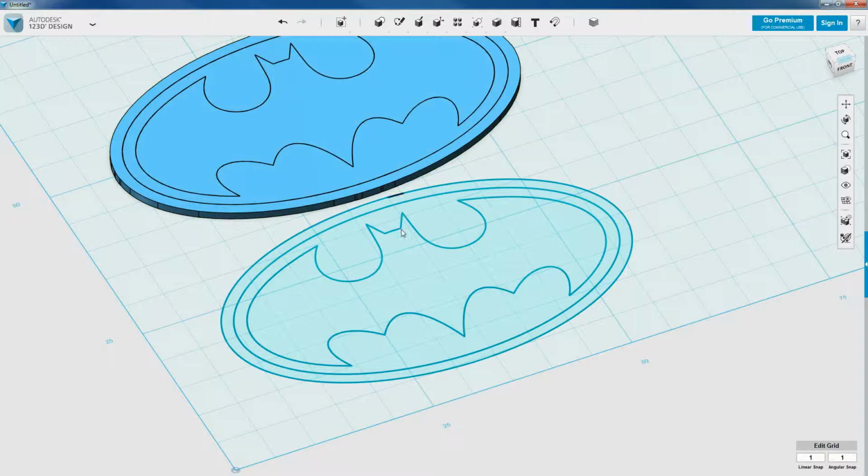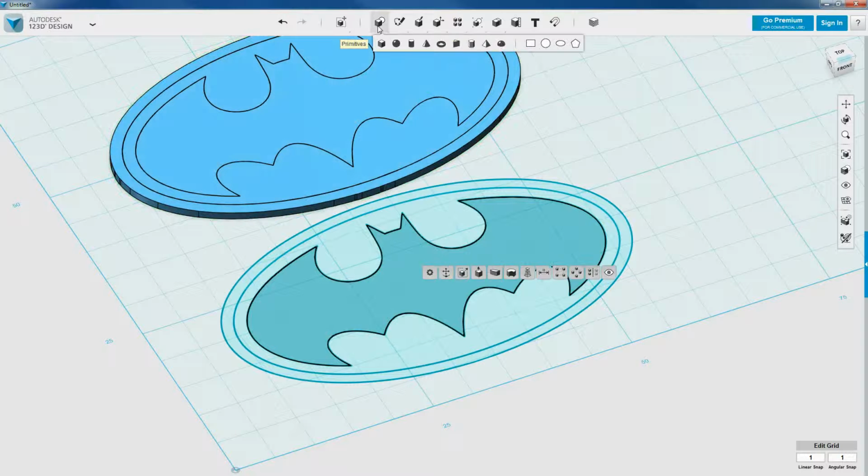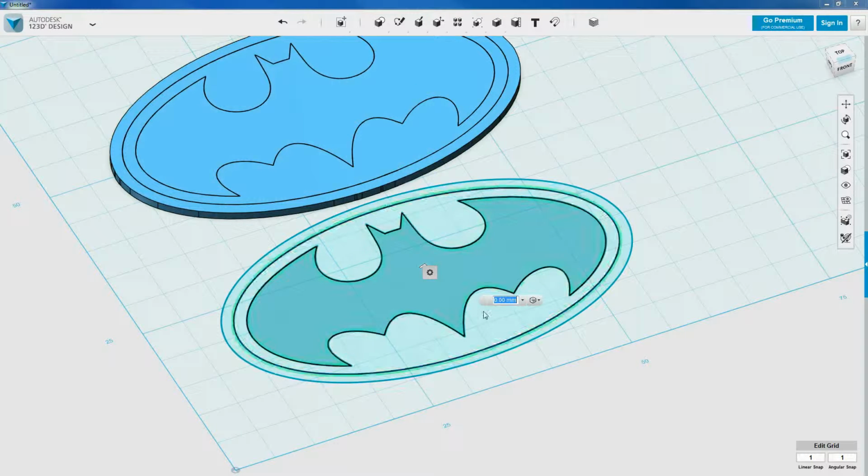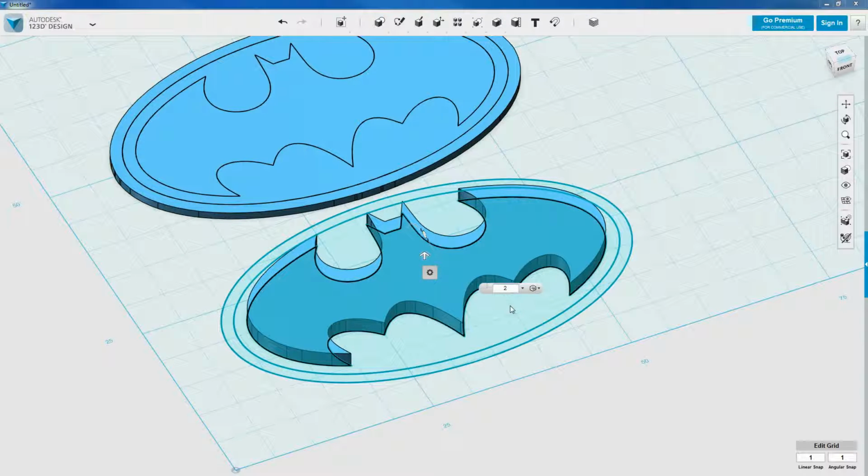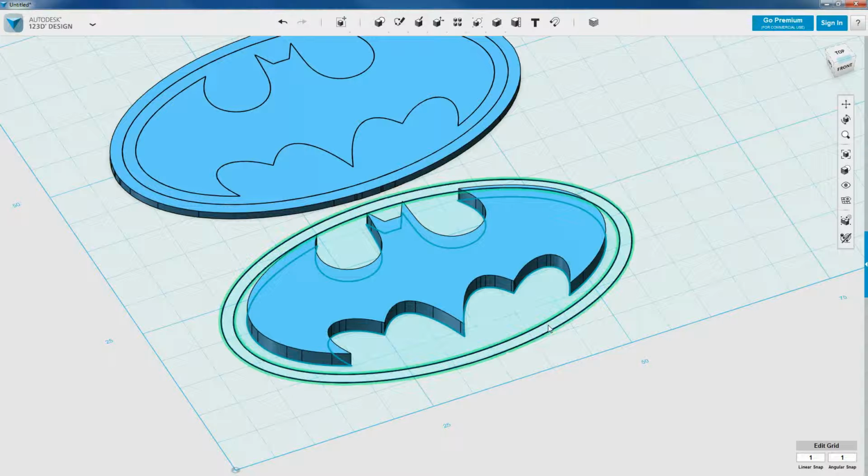Okay, what I now want to do is bring this shape up here. Let's come to my extrude tool again. And of course, this is right on the middle of the arrow, typical. I'm going to bring this up 2 millimeters. That's looking quite nice. I'm going to select this edge here, and I'm going to try something a little bit different here. I don't know if this is going to work. I think there's going to be a problem. Let's bring that up 1 millimeter.